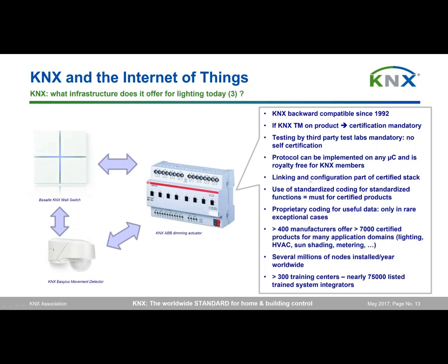The KNX protocol can be implemented on any microcontroller and is totally royalty-free for KNX members. The linking and configuration of products is part of the certified stack. So the communication with the ETS software is also part of the certification. All products make use of standardized coding for standardized functions. And proprietary coding for useful data is only accepted in very rare cases.